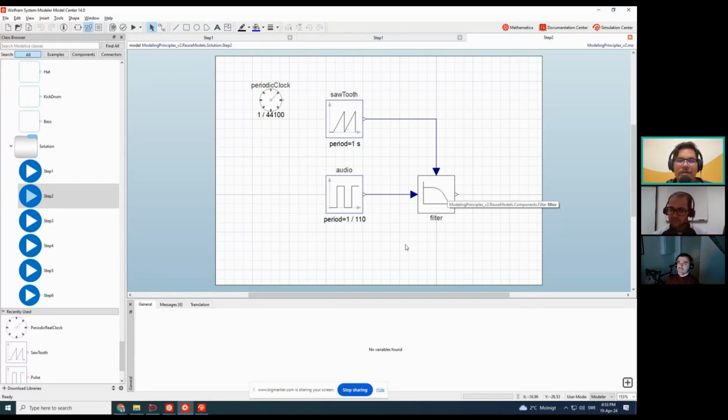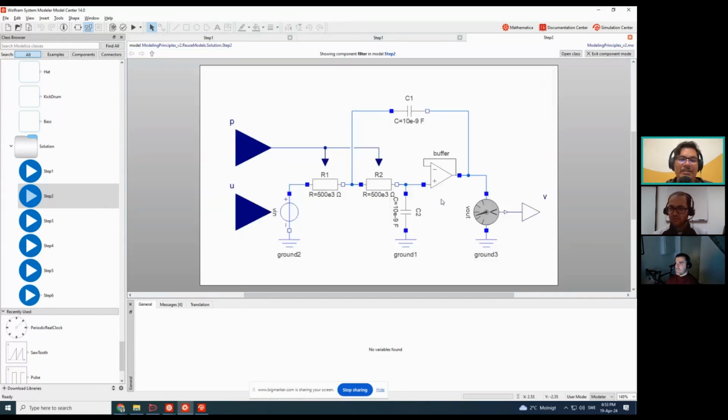Yeah. So the first one is a single pole filter. What that means is that it filters, but it's not very good at filtering. This other design, the Sallen-Key, is a second order filter. So it's basically twice as good at removing frequencies, and in practice it will produce a smoother sound. And in synthesizers, there are also very common fourth order filters, which filter even more.